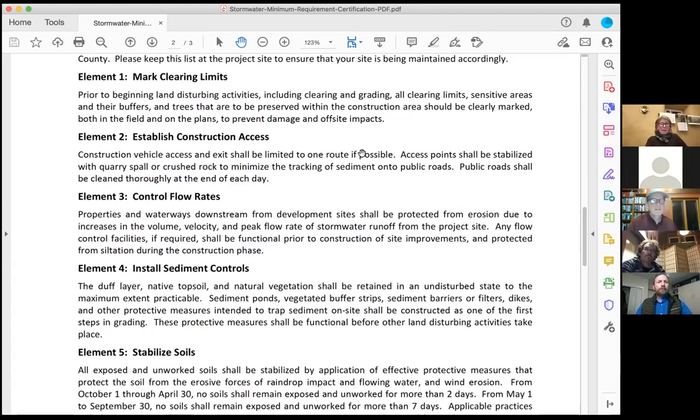Yeah, I can't stress that enough. Staking and marking things out is just kind of the basis of what we call low impact development. It's just part of good planning to really mark out where excavating equipment is going to go and not go. You can make a huge mess and it can be total chaos unless it's really planned, it's really marked well.